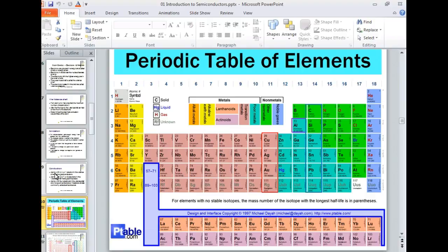If you're going to deal with aluminum, and my son's got aluminum in his house. His house is pretty old, so his house is aluminum wire, and he refused. He won't buy a copper plug since I told him that, even though you can buy a paste that you put around the aluminum to keep it from oxidizing. You can't keep it from expanding and contracting, but you can keep it from oxidizing and messing up your copper wire.